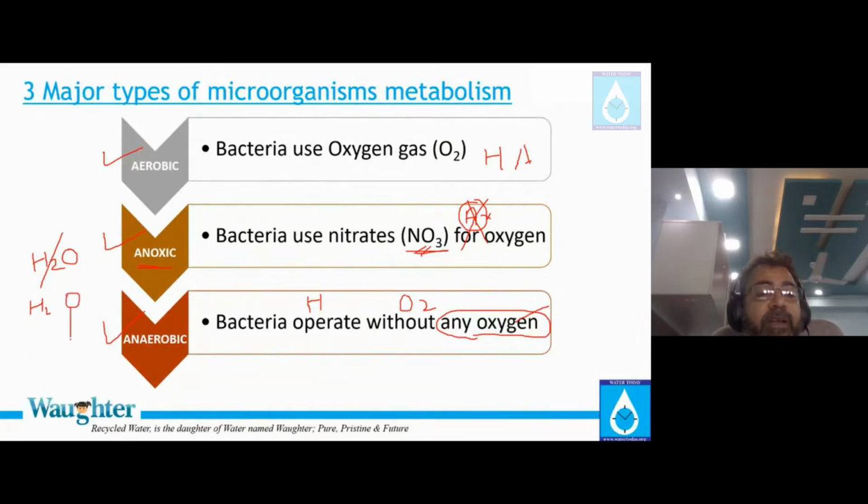Remember, C5H7NO2. That has to be made. So oxygen goes in the body of the bug. So what will the hydrogen do? Hydrogen will say, come on, you cannot leave me naked like this. I am the most aggressive material. So hydrogen, at that time, nearby acid available is acetic acid. It will strip acetic acid and take all carbon from there and become methane. So the final methanogenesis process will happen because the trigger is the need of oxygen for the cell synthesis.